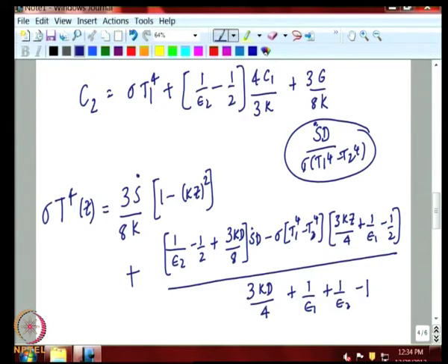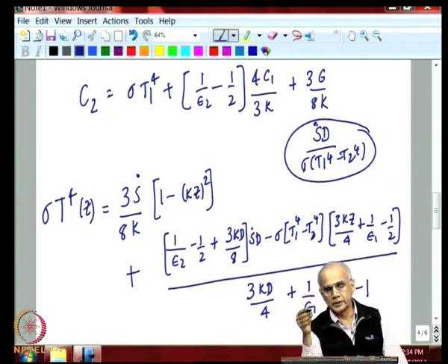So, for example, if you are dealing with a problem of combustion heat transfer in a furnace, and you have an idea about the rate of heat generation due to combustion, then by calculating this parameter a priori, you will quickly get a feel for how important the heat generation term is vis-a-vis the wall fluxes.